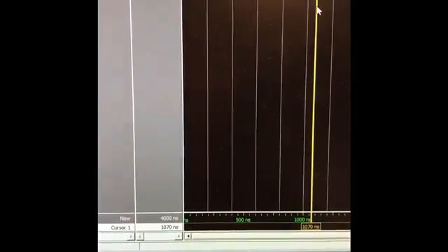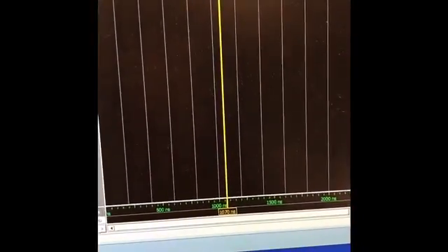Your next state should be the NOR function. And it is right, so 0 and 0, because there is not a 1, you're going to get a 1, which you do. 1 and 0, 0 and 1, and 0 and 1. Because there is a 1, the way the NOR works, you should get 0 outputs, which you do. And so we know that that state works here for this number.